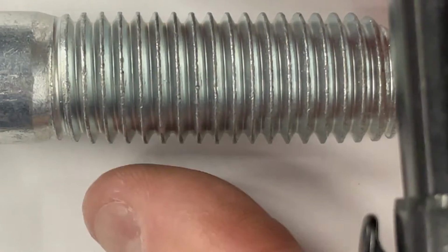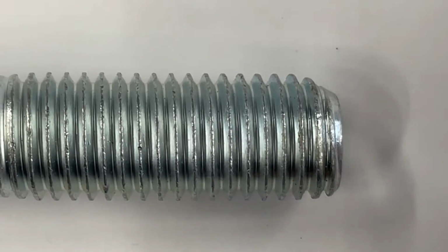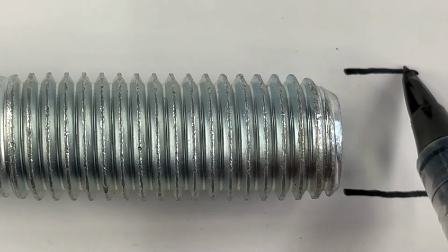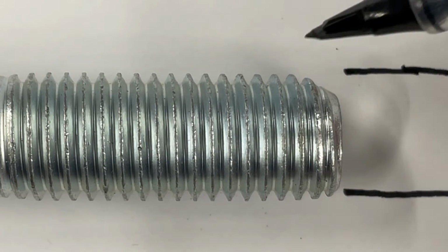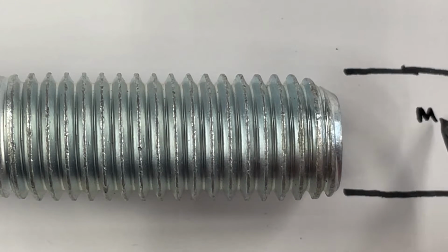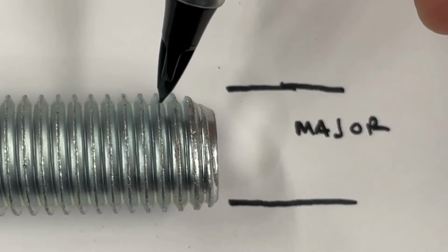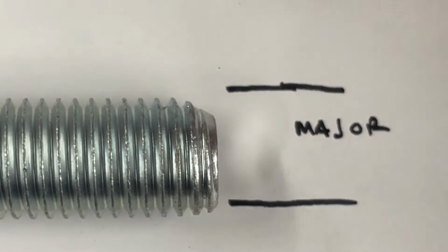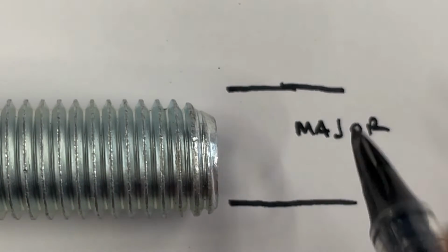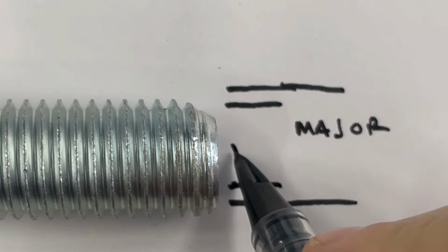Now looking at this fastener, we have a few different terms that we need to figure out. The first one is the major diameter. The major diameter is from the outside to the outside on the other. So that's our major diameter. And then if you look inside, we have the valley of the thread, and it goes all the way inside. If we go from the inside, or the root, which I'll define in a second, to the inside, that's a slightly smaller distance, and that is the minor diameter.